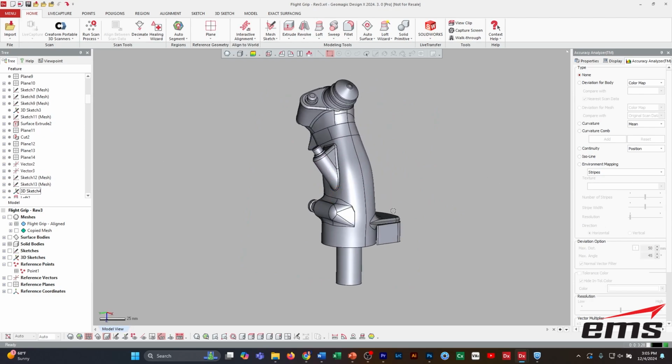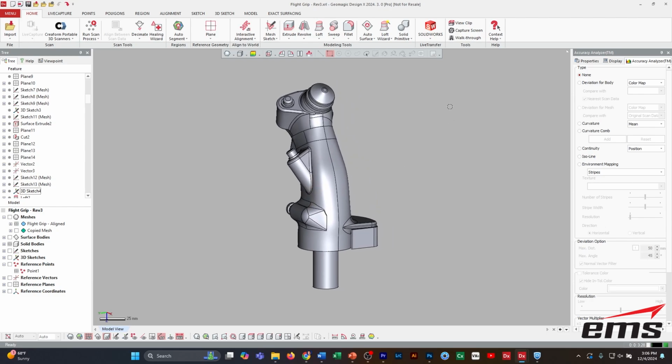Now, the other thing, once this is done, we can export it as a STEP or Parasolid or IGES file, and that's the same for all of them. But what we can also do here is what's called a live transfer from DesignX. And if we look here, we have it for SolidWorks, Creo, Inventor, Siemens NX, and AutoCAD. What that'll do is go over here to this history tree, roll back, and actually transfer all of these features into your host CAD system. So if you want to make further changes to it, you can do that.